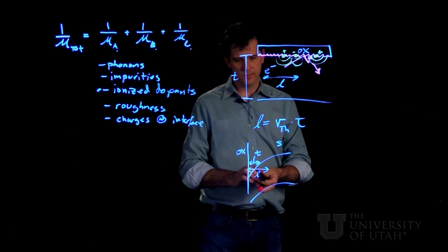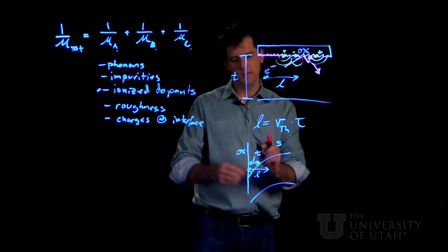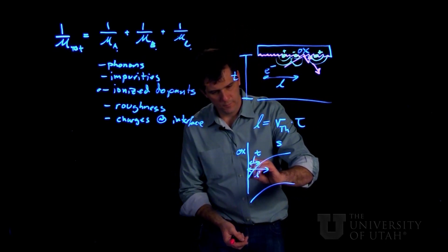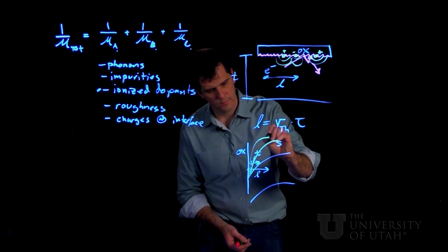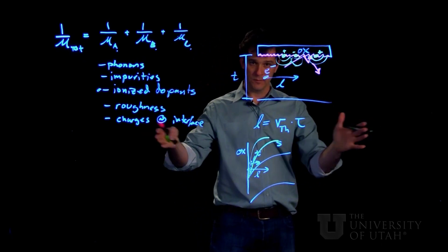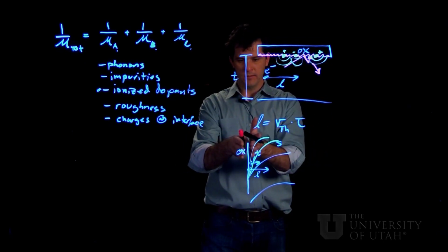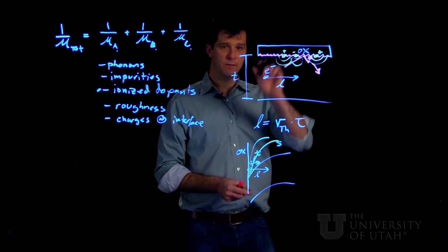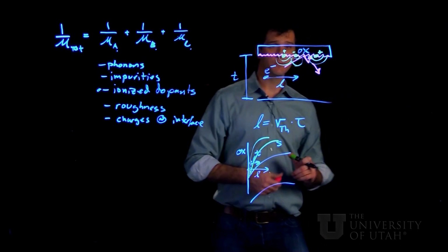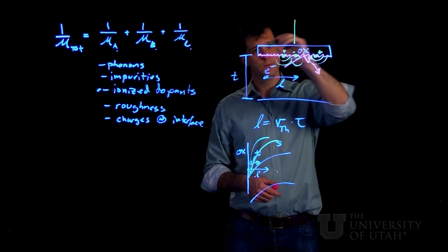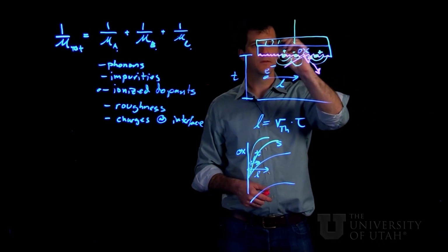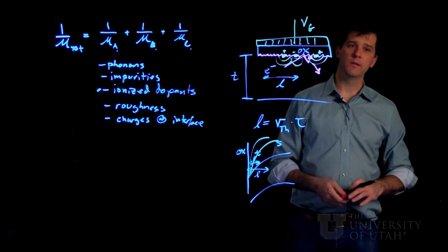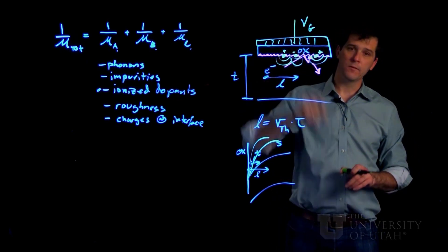And lastly, this sort of confinement distance here, T, is going to change depending on what voltage we apply. So for very high voltages, we'll have our bands bent steeper and steeper, and thus this thickness will be sort of smushing the electron inversion channel closer and closer to this oxide, enhancing these effects of the roughness and Coulomb scattering. So we should expect then some dependence of the effective mobility in the channel related to the gate voltage.